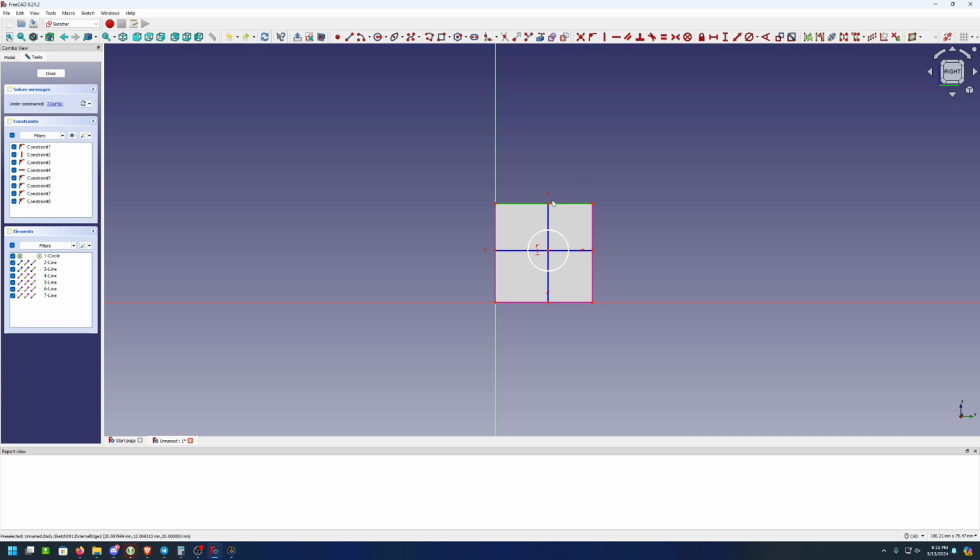I grab the line, I grab the dot, equals. I'm hoping that gets fixed in a future update, because I have not been having issues in FreeCAD. It's been a very smooth experience, except for these redundant constraints. They can just be deleted. It immediately knows, and I delete the one it tells me to delete, and it works.